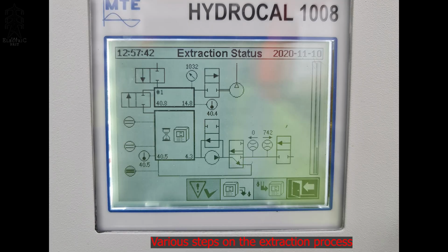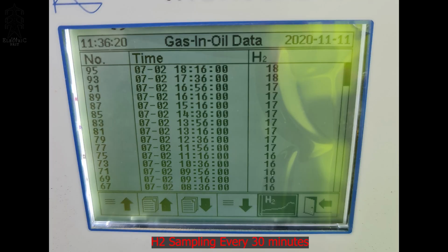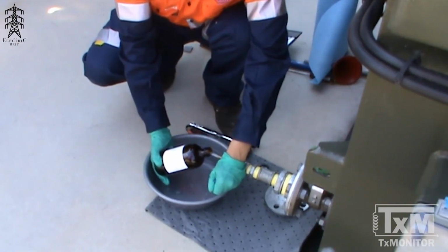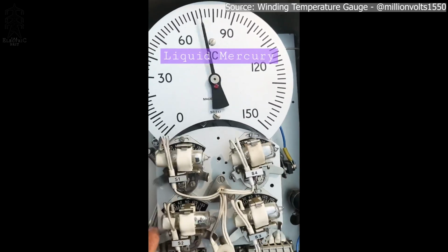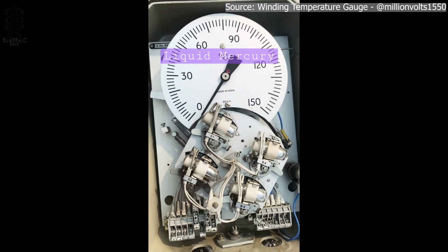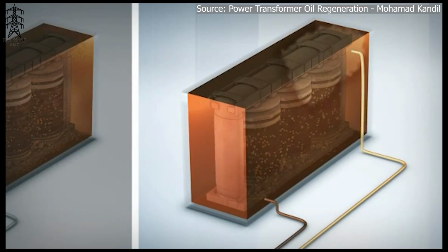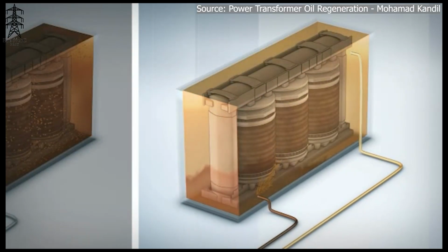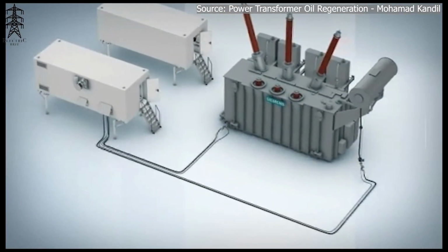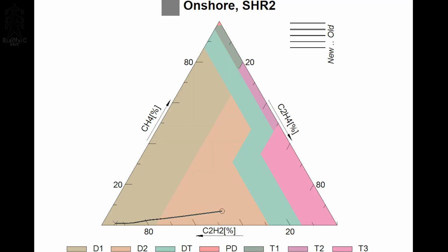Dissolved gas analysis usually happens in intervals of anywhere from 15 minutes to hourly or more, and isn't fitted to every transformer, especially older ones where an oil sample is taken usually by bottle and sent off to a lab for analysis. So to help protect the transformer even without DGA, we rely on the Buchholz relay, WTIs and OTIs as described earlier. Transformer oil needs to be regularly reprocessed to remove moisture and contaminants, which can reduce its insulating properties. However, in older transformers, this regular reprocessing might mask faults over time, so interpreting the oil test results is super important for your supergrid.